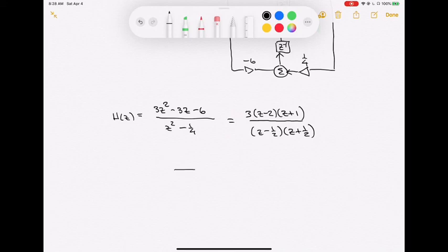So this series realization just needs to be done something like what? I know that if I have systems in series, right, some system followed by another system, where I have an input X and an output Y, call this first system some H1 transfer function, and this other one H2. The overall equivalent is H1 times H2, right? We'd seen that before. If you had systems in series, in the time domain you'd convolve their impulse responses. When you go to the transform domain, convolution becomes multiplication, so you just multiply their transfer functions. So I can look at my H of z and say, can I break this up into something times something? And certainly I can do that here.